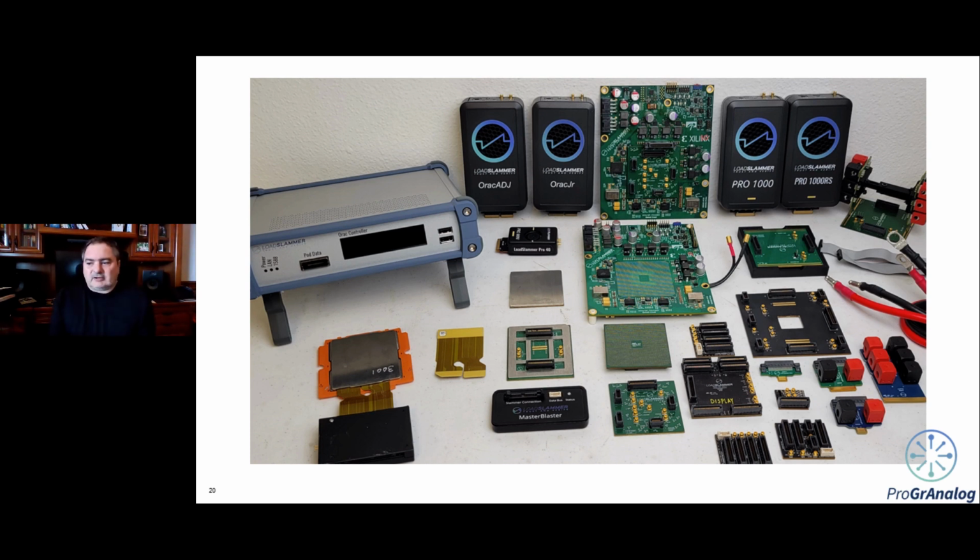The ORAC controller is able to do multi-rail slamming simultaneously, so that you can test for cross-regulation: if one rail suddenly gets hit, does it affect another rail? And then you can stack these, or parallel them, so they will be time synchronous, so you can do concurrent slamming and measurements on as many rails as you want.